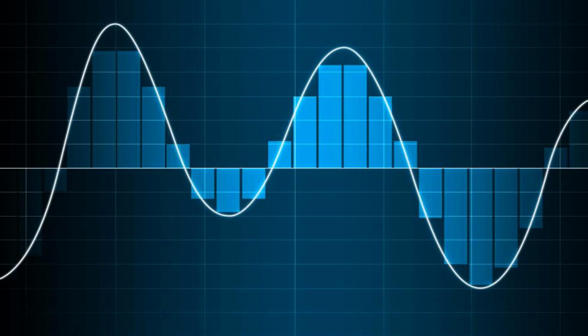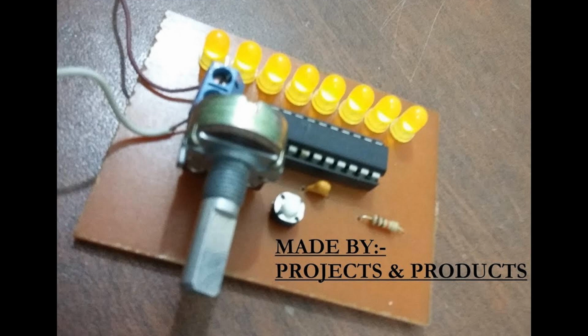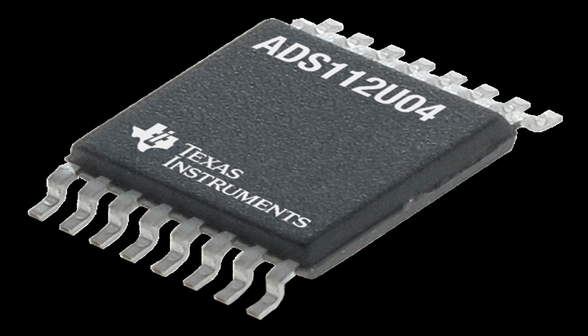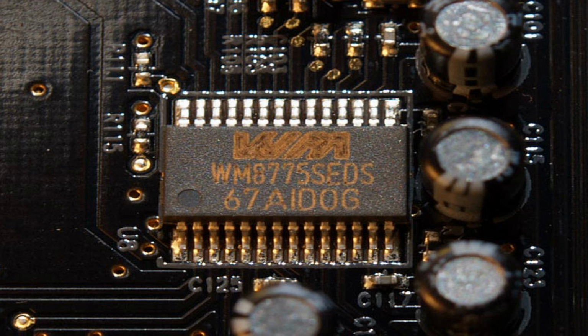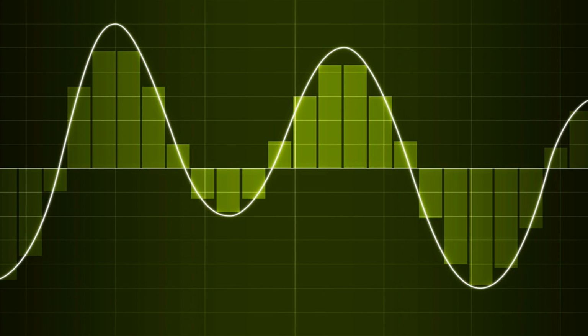The ADC is a piece of hardware that takes in the analog signal as input and produces a digital signal as output. The ADC essentially samples the analog signal at a specific frequency, and quantizes the amplitude of each sample into a set of discrete values. These values are then combined to form a digital representation of the original analog signal, which can be stored on a memory card or other storage device. In the next section, we will explore how the ADC performs this conversion process in more detail.